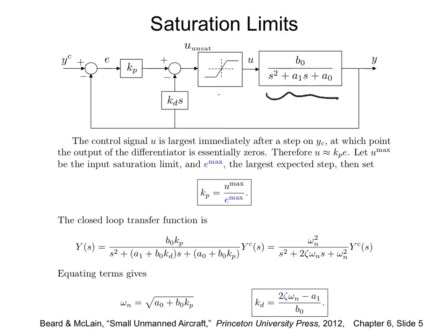So basically what we are saying is your U is limited by U max and U min, right? The system cannot apply more than that particular input. So you put a saturation block: whatever the actual output of the controller is, you pass it through this saturation block. That means if your output is greater than this value here, it will curb it. It will make it constant. So this is U max here and this is U min here.